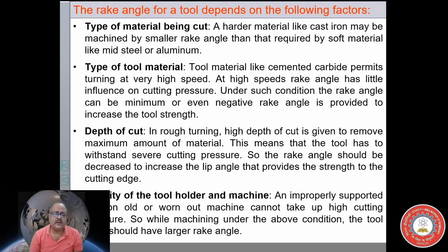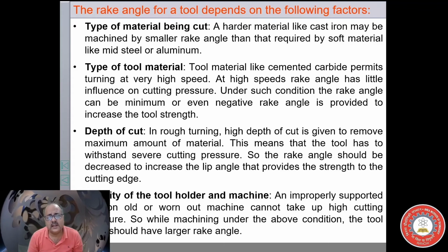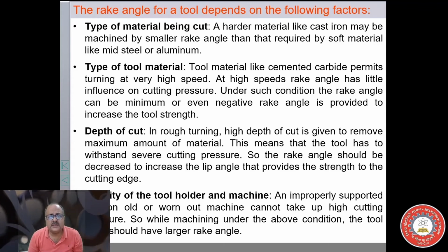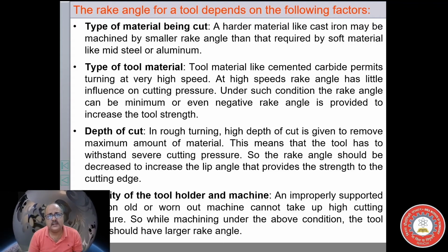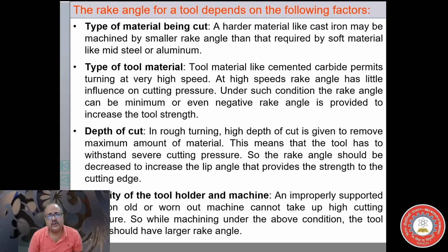So there are several factors based on which we select the rake angle, but you don't have to worry. As a machinist, there are often handbooks available for a particular combination of tool and workpiece material and the cutting speed that you are selecting. There is a recommendation of rake angle, and you can select a rake angle.